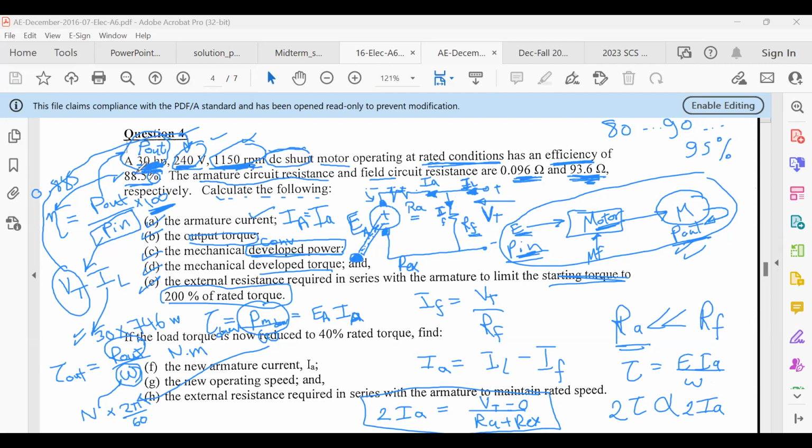So what is the 30 horsepower? It's the rated power of your motor at the end of this shaft. However, in between, you have some losses, for example losses from the resistance of the air. We call it windage. We still have core losses inside your core, which are the hysteresis and the eddy current. So you have the stray losses, of course, if present. So you have some losses between the developed and the output.